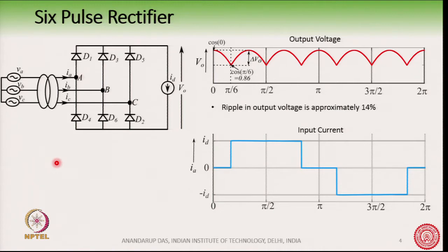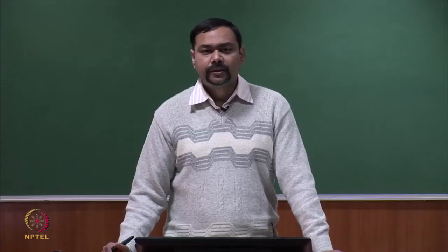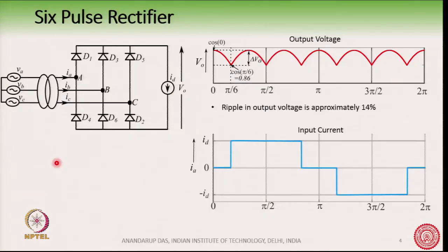For example, people typically choose transformers having leakage impedance of say 5 to 6%, typically 4 to 6%, and it cannot be made very small, because during a short circuit on the DC side, the transformer impedance is the element that limits the rate of rise of current. So, it plays an important role apart from isolation.